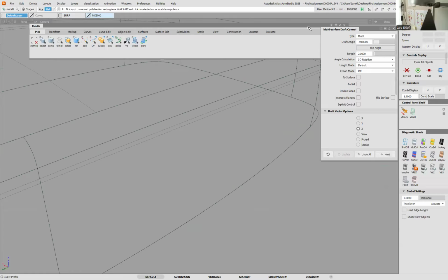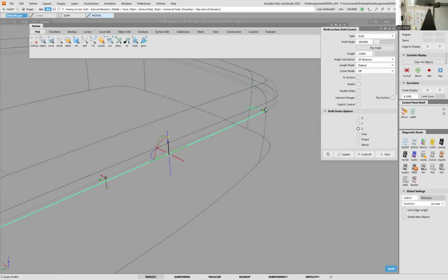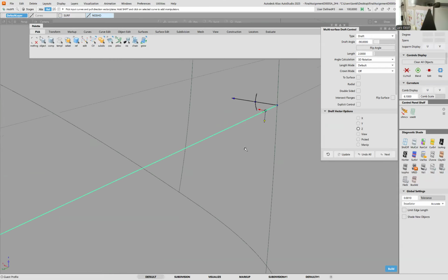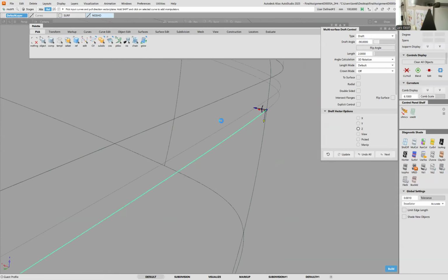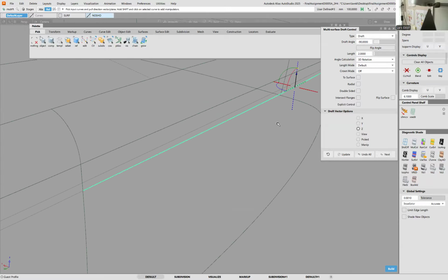So I use this tool to create an angular surface towards another surface. And I set the angle to 90 degrees or minus 90, depending on how it counts. So I click on my curved surface like that, and I get a proposal, which we can see here. It's going to point inwards, which is exactly what I want, at 90 degrees.